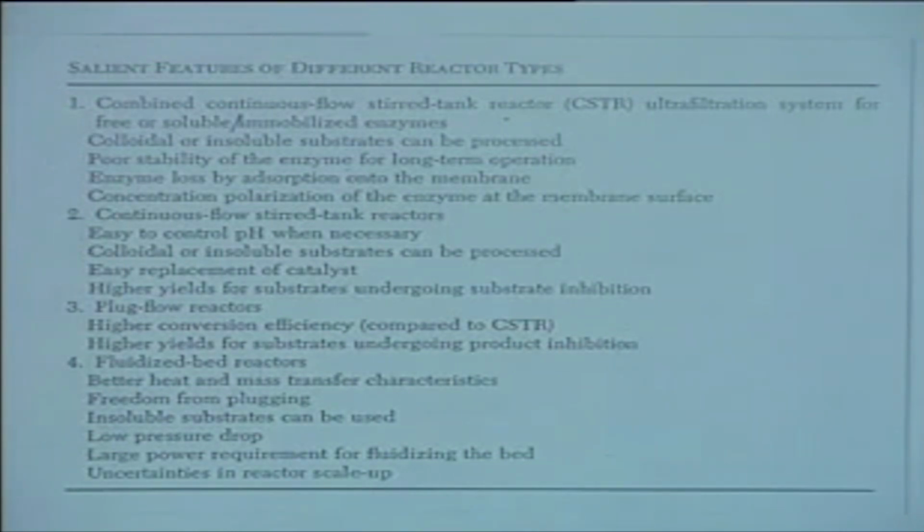And particularly in the case of even a CSTR, if you handle enzymes that are shear sensitive, or carrier particles which can undergo a lot of attrition during use, the CSTR becomes a sort of disadvantageous system, because if the carrier particles get disintegrated during use, it will involve the loss of enzyme.